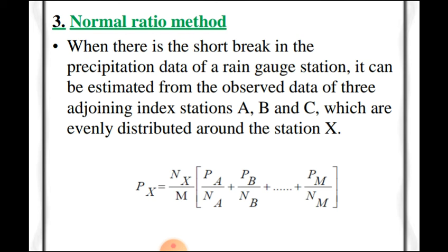Generally, the value of k we consider here is 15. P bar plus k into sigma. The mean rainfall plus 15 times the standard deviation. This is taken as the possible maximum in the mathematical calculation for that area, and it is used in critical designs to estimate the maximum floods which can occur in the given catchment.